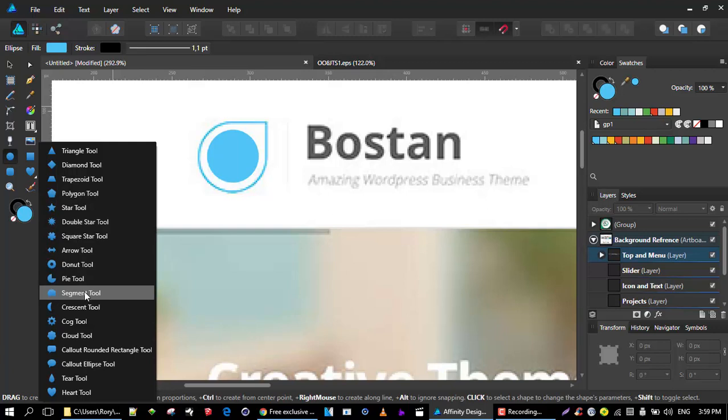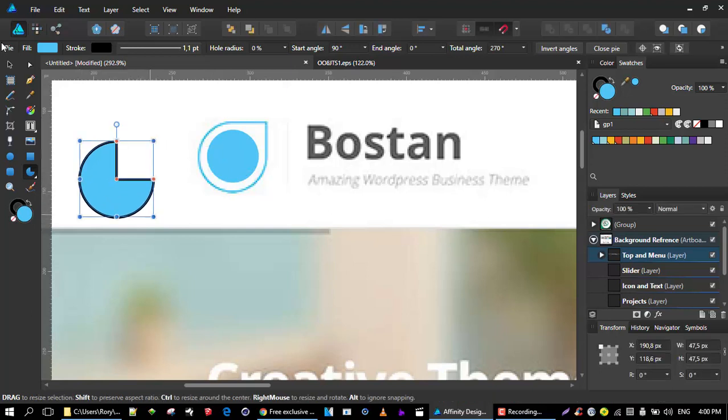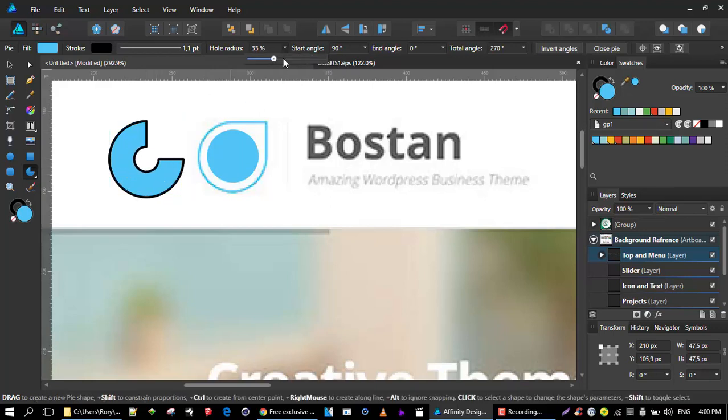We're coming to another sort of exciting space of design. So I'm going to use the pie tool. I don't know if it will really work for what we want to do. But a parametric object is an object that's created from these shapes, but they have little handles where you can do precise measurements with them. You could even type in the information. If I'm selected here, to be able to see the handles, I go onto the actual parametric area. When I click there, you'll see these red handles. So when I start making movements, you can see these. And I could also just type it in here if I do these measurements.